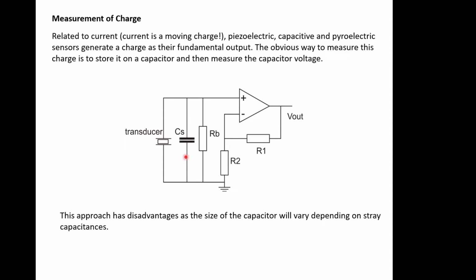The capacitor is just a device in itself, so there's no mechanism for getting bias currents into this device here. So we provide a big resistor to ground, which allows a current to flow through here to allow the bias to happen. Otherwise, if we didn't have this, we would run into problems with this configuration, even though what it looks to be doing is sort of making sense.